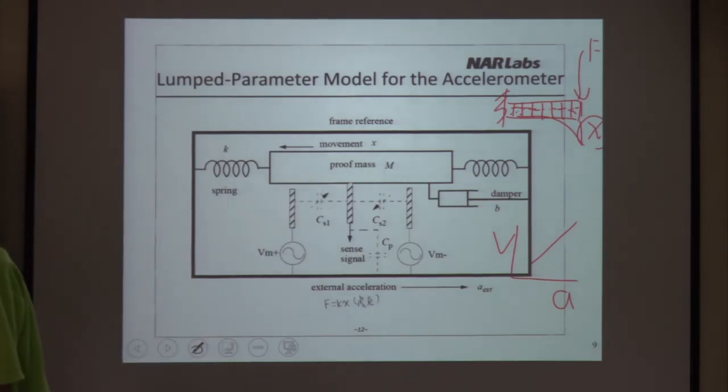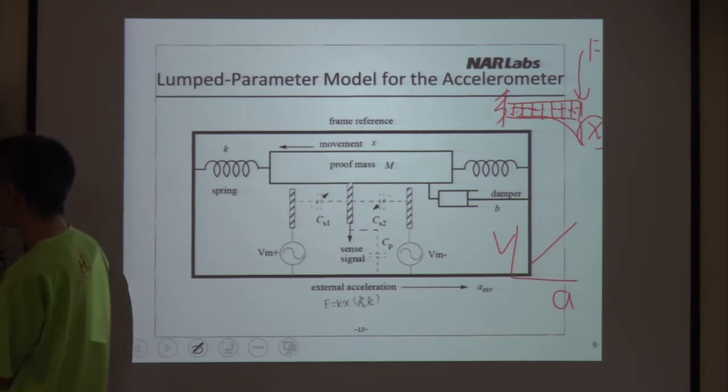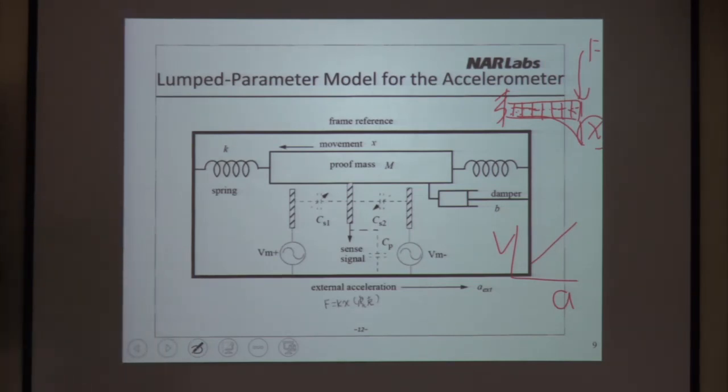But also you can model this beam as only one mesh. So here is a spring. So you apply force F. You can get the same displacement, X. So we create this model with only one point to represent this beam. So this is lumped model.